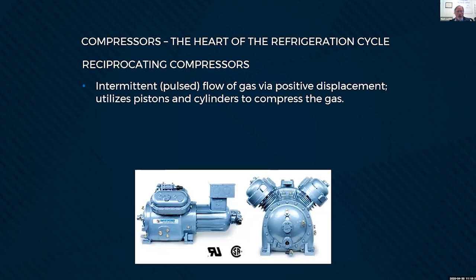So the heart of the refrigeration cycle is the compressor, several different types. The granddaddy of them all is the reciprocating compressor. Basically, it looks like a piston-driven engine. It's got pistons in it, and that pulsed flow of gas results from the positive displacement of the pistons. So it's not a continuous flow.